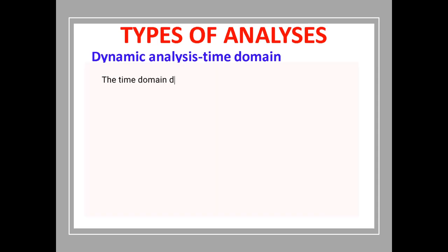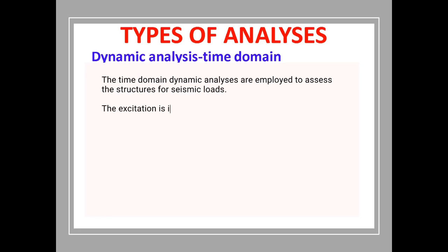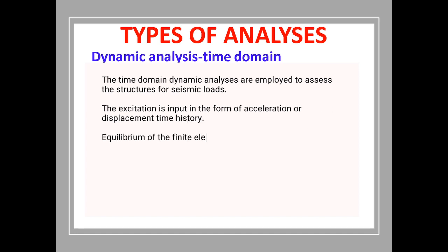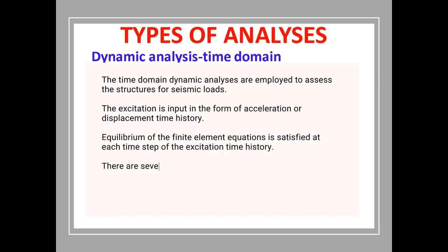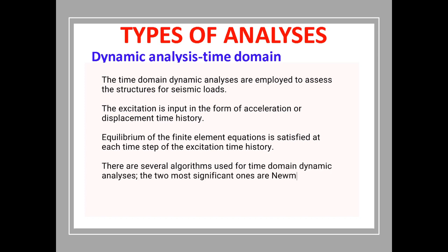The time domain dynamic analyses are employed to assess the structures for seismic loads. The excitation is input in the form of acceleration or displacement time history. Equilibrium of the finite element equations is satisfied at each time step of the excitation time history. There are several algorithms used for time domain dynamic analyses. The 2 most significant ones are Newmark's and Wilson's methods. The analysis can be performed linearly or nonlinearly.